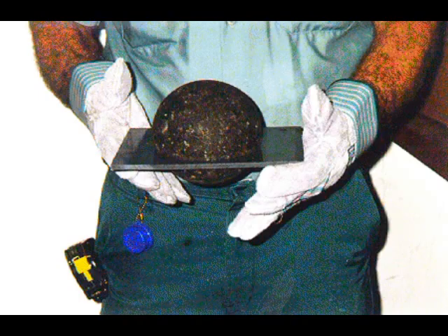Periodically, check the amount of wear on the ball check valves. Tools can be made to allow a quick check of the wear on the ball check valve. The check valve in this picture should be replaced when the entire ball fits through the hole in the PVC guide. Refer to the manufacturer's literature for requirements and limits of wear. One manufacturer, for example, allows a 16 mm (5/8 inch) decrease in the diameter of a 125 mm (5-inch) ball before replacement is necessary. This is about a 30% decrease in the volume of the ball.